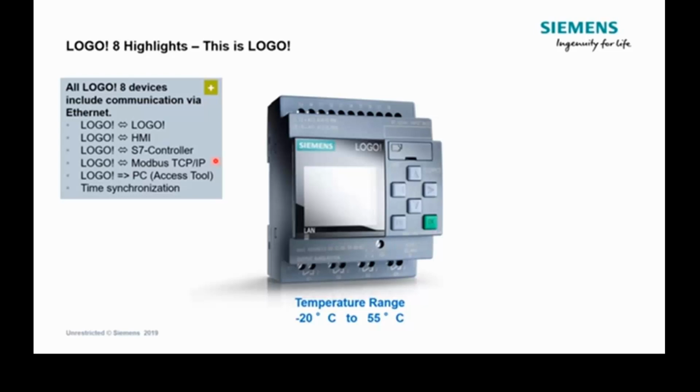So as an example, an S7-1200 sat as the main controller over a network can then communicate down using Modbus TCP to a number of Logos down on a lower level network that maybe then have some individual tasks or gather some sensor information in to push back up to us as the main controller in the 1200. So again, good flexibility and use and integration into the wider third-party systems out there.